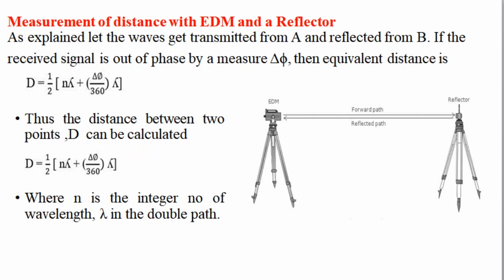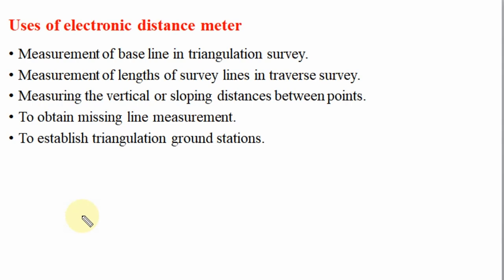Okay. Then uses: measurement of the baseline in triangulation survey, measurement of the length of the survey in traverse survey, measuring the vertical or sloping distance between any points, to obtain missing line measurements, and to establish triangulation ground stations.